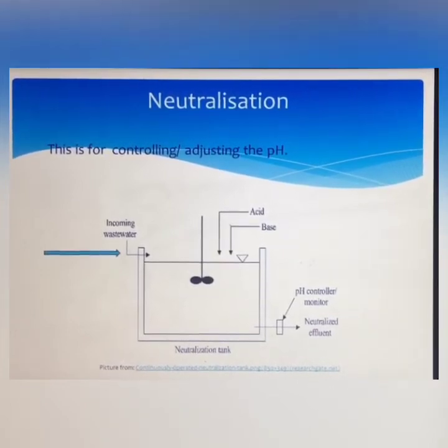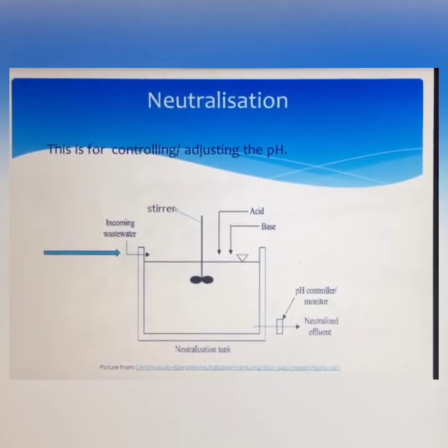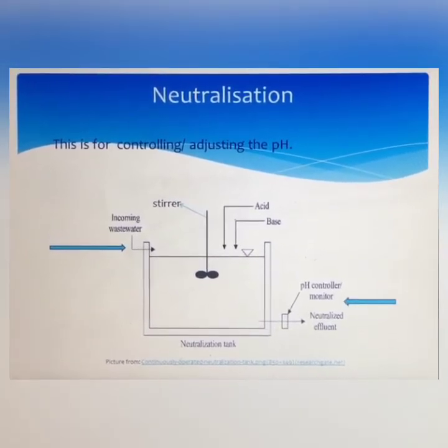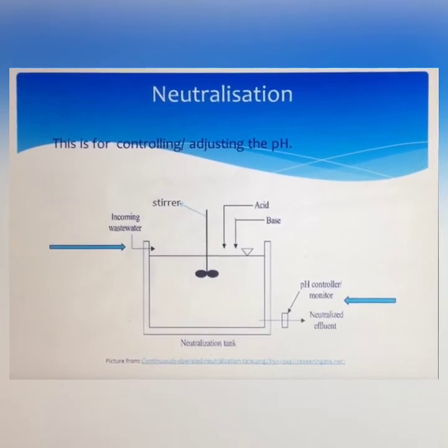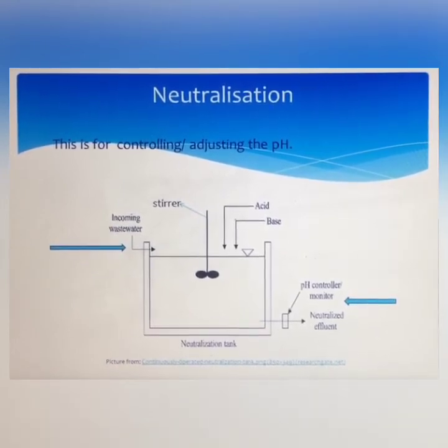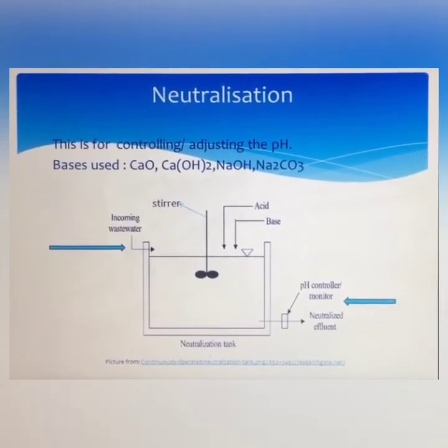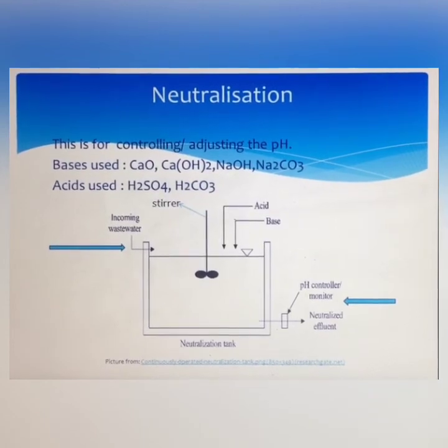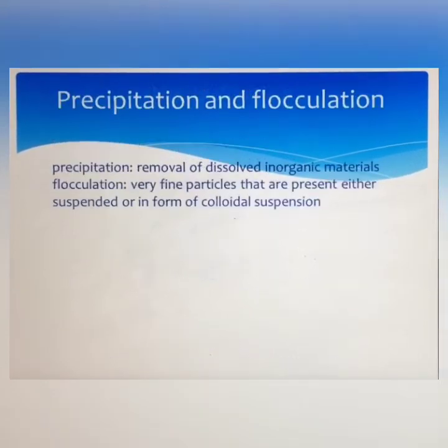As the wastewater enters the neutralization tank, it is stirred completely. This is to ensure that the contents in the tank are uniform throughout, so that when the pH monitor measures the pH of the water, it reads a value corresponding to the contents inside the tank. If the water is acidic, then a base is added to neutralize the acidity and adjust the pH to an acceptable range. If the water is basic, then an acid is added to neutralize the alkalinity of the